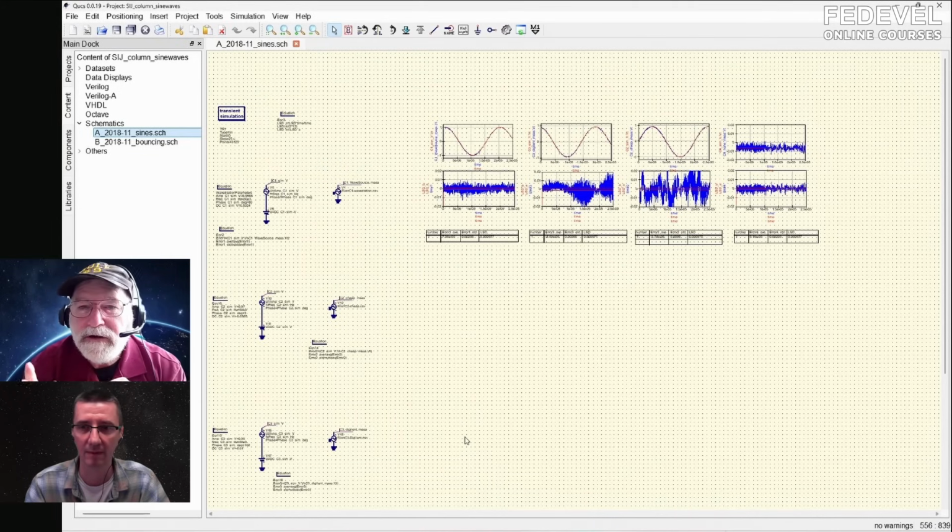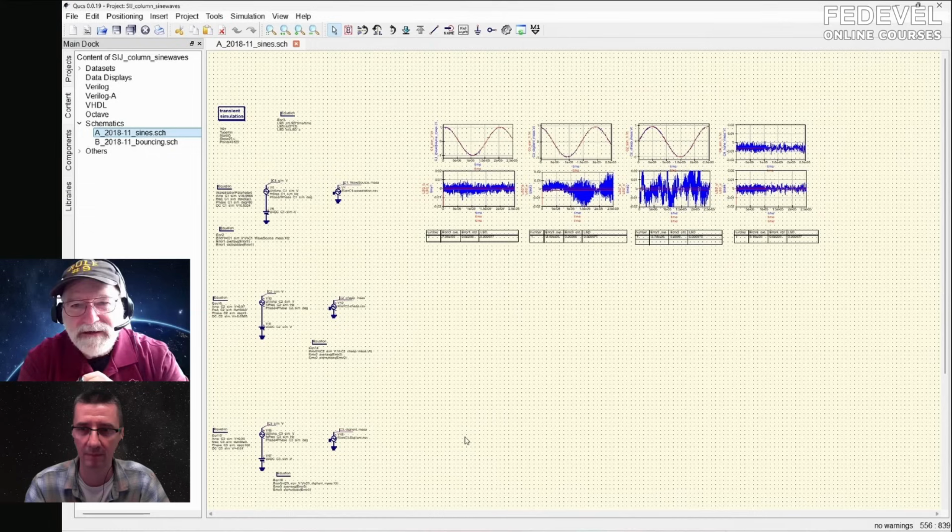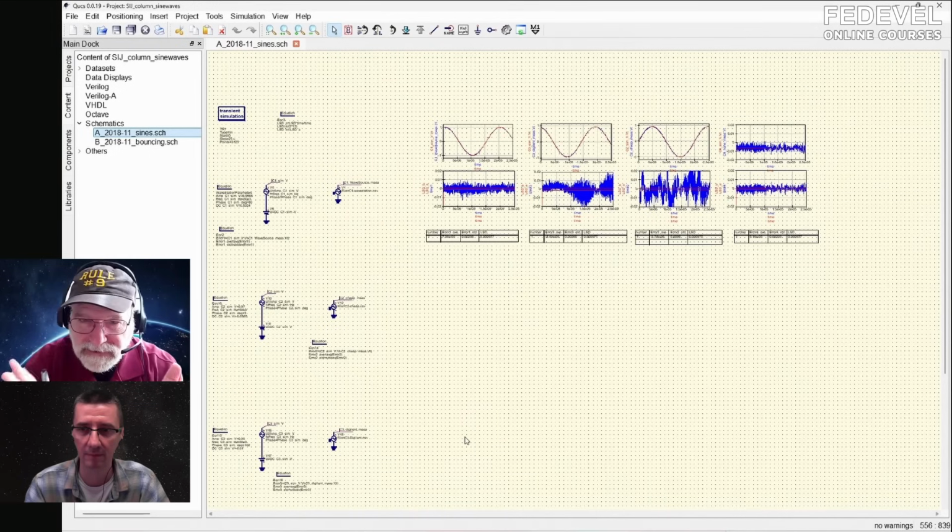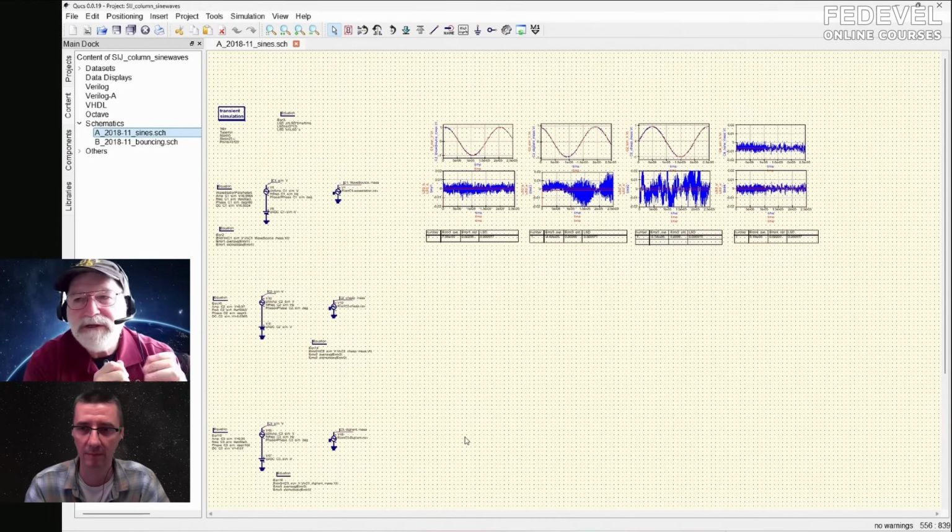There's another free tool from Sierra Circuits on their website that will allow you to do just what you said. You type in the trace width, the thickness, the dielectric constant, all those features of the stack up of the transmission line, and it will calculate for you based on a 2D field solver. It will calculate the characteristic impedance and the time delay. And that information is what you put into Qucs when you build your circuit topology.